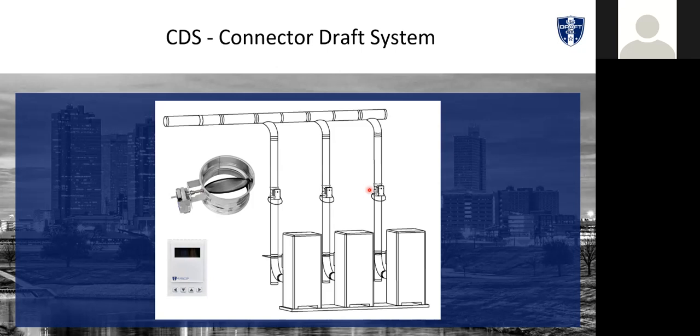So if we set it with a slightly positive at each one of the appliances, then we can set the combustion. It's just getting when we set the combustion, we really want the pressure to be constant. That's what gives us that good continued combustion. So if I could guarantee you that you're always going to be plus or minus 2/100ths of an inch from whatever that set point is, that's going to make your combustion a little bit better, correct? Yeah, of course. It makes it much more repeatable, and which in turn makes the appliance more efficient. Exactly. So every commissioning agent that I introduce this to, they want them on every boiler. Now, obviously, there's cost involved, there's logistics involved, but it really allows, like he said, it allows them to now set their combustion, knowing that my draft is always going to be consistent. It's always going to be whatever X is.